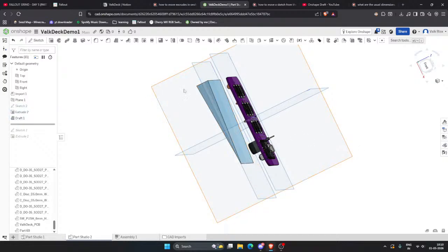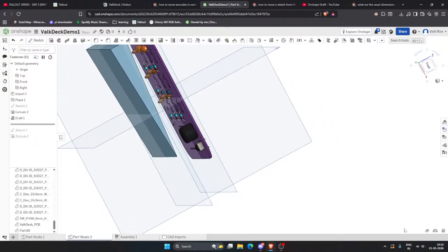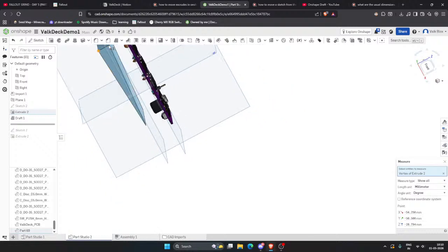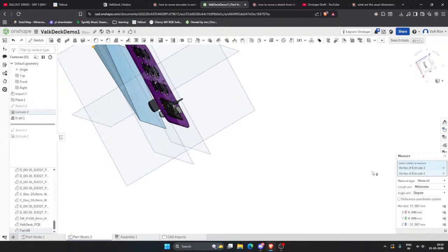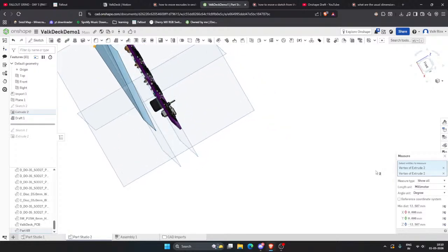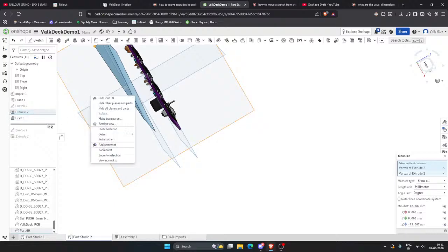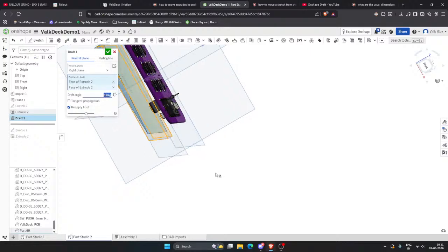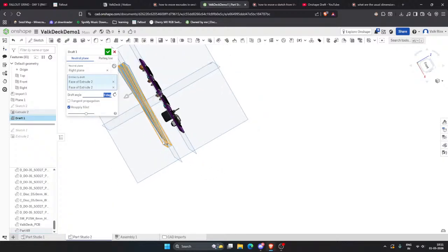Don't even need something like 4 degrees because let's check the measurements. 1.2 that point. We will get around 12.587 millimeters, which is good enough. That's 1 centimeter. Let's make it a bit less. So decreasing draft angle by 3 degrees, 3 degrees that is. You'll get this. But initially, our thing was a bit longer, I have to admit.